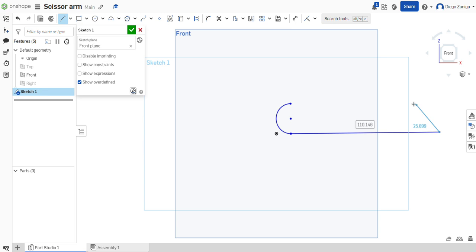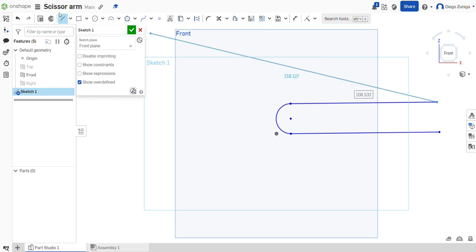And if I don't unselect this tool, it's still going to try to make some extra lines. So I'm just going to click unselect or hit the escape button. I'm going to make another line coming from here, let's say there. And then I'm going to make another arc. And there. Now we have a shaded area, which is an enclosed area in this software.